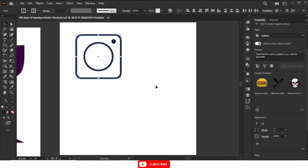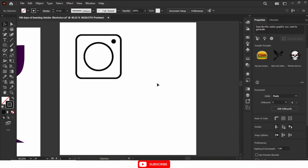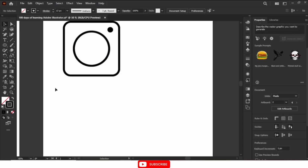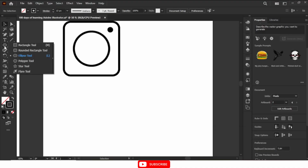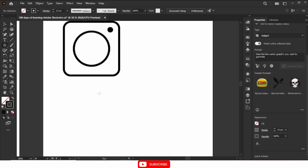Now let's create another icon. We're using this to learn how to use shapes in Adobe Illustrator. So let's create our arrow. Selection arrow. Go back to your shapes tool, right click and expand it. Grab your star tool here, click on it. Then to draw out a star, same way, click and drag.